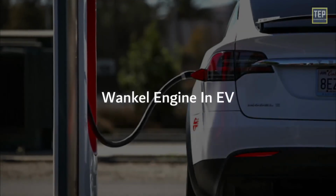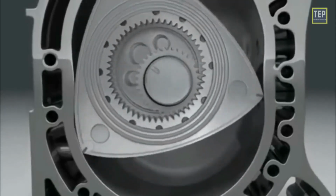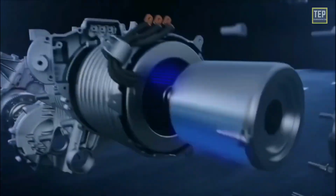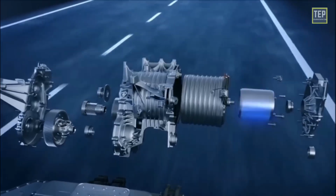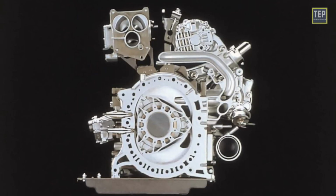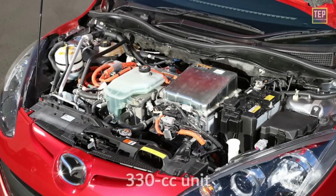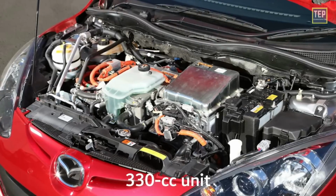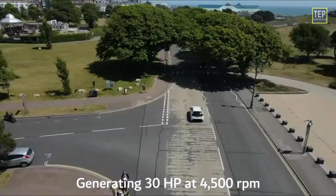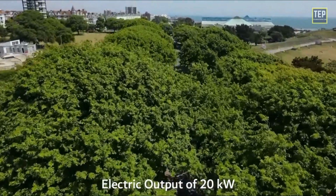Wankel engine in electric vehicles. This time, the rotary engine itself will not actually propel the car. Instead, it will generate electricity to power the electric motor and other systems in the car. The Mazda 2 EV uses a Wankel engine as a range extender. The engine is a tiny, almost inaudible, single-rotor 330 cubic centimeter unit, generating 30 horsepower at 4,500 RPM and maintaining a continuous electric output of 20 kilowatts.